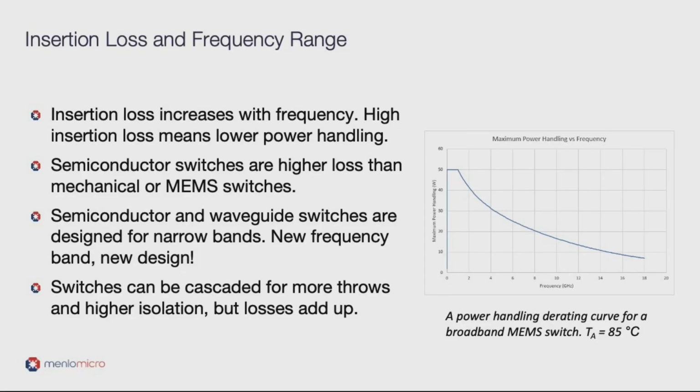The first spec you'll likely look at is insertion loss. This is usually an important system requirement, but it'll also directly affect the power handling of the switch. A broadband switch that advertises 50 watts might not be capable of 50 watt handling over the whole band, and this is because the insertion loss will change and increase at higher frequencies.